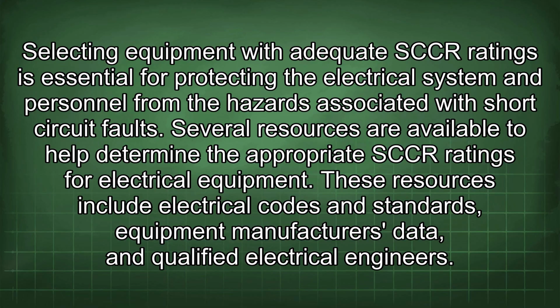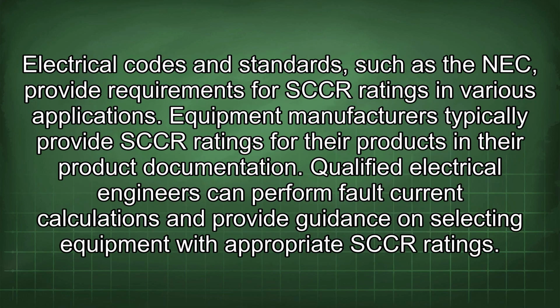Several resources are available to help determine the appropriate SCCR ratings for electrical equipment. These resources include electrical codes and standards, equipment manufacturers' data, and qualified electrical engineers. Electrical codes and standards, such as the NEC, provide requirements for SCCR ratings in various applications. Equipment manufacturers typically provide SCCR ratings for their products in their product documentation. Qualified electrical engineers can perform fault current calculations and provide guidance on selecting equipment with appropriate SCCR ratings.